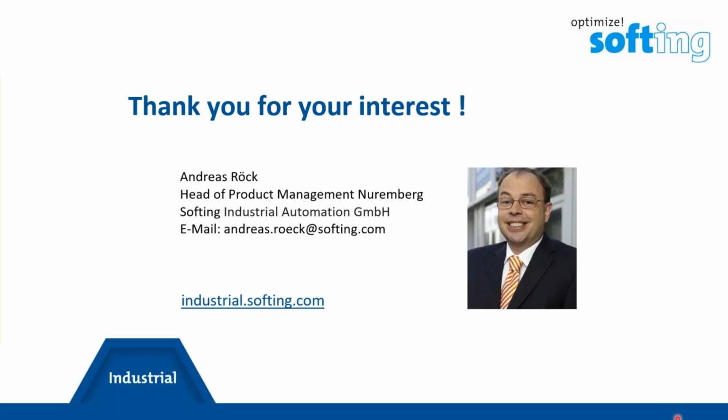First question we already received from Mr. Van Eybergen: Is it possible to create your setup in an external file and import that? Yes, but it's not one file. The suite configuration is organized in multiple files. For example, for the database connectivity, you must edit 2 files. One is a subscription and the other one is a task file. In these 2 files, you define all the actions for the database, also the variables which you want to store, and so on. It can be configured via files, but these are different files.